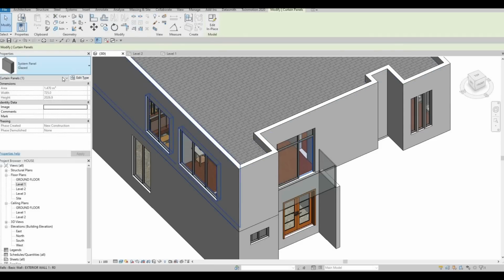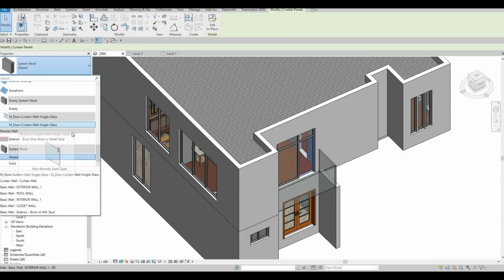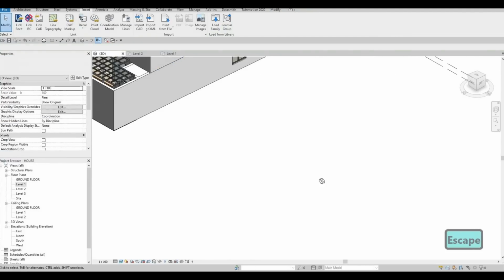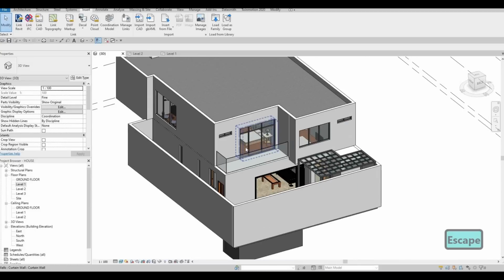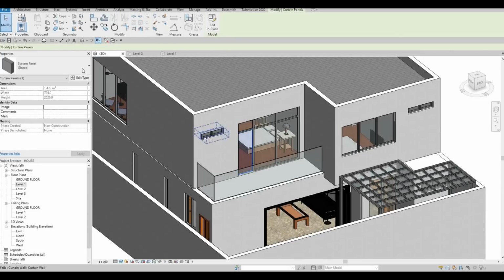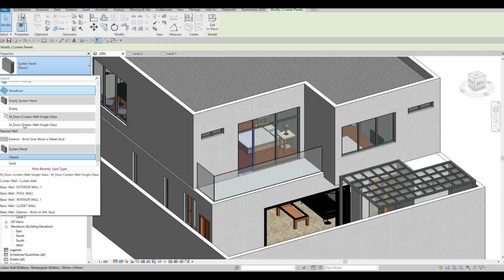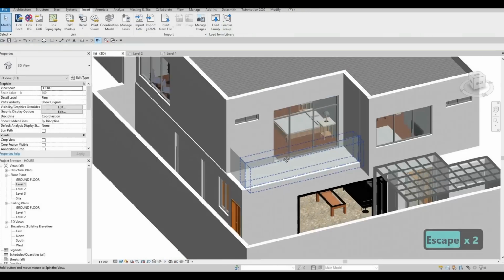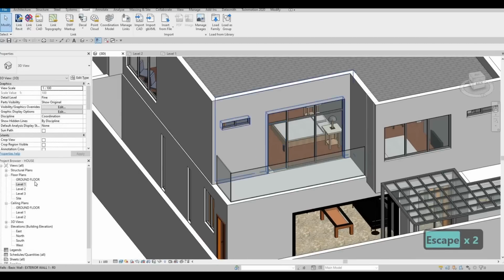And then after that, go to drop down and then select that door that we just added here as well. So let's do it again. Click on tab multiple times until you have that panel highlighted. Select that and then click on drop down here. So that's how you add those curtain doors.